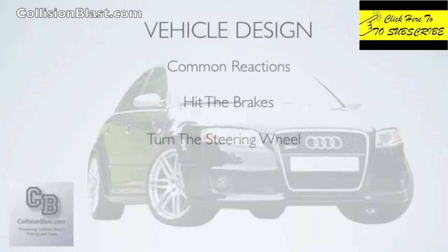The second thing that you're probably going to do, just out of natural reaction, is swerve one way or the other. So you're probably not going to hit them straight on. You're probably going to swerve the wheel just a little bit, and by doing this, it's going to cause the front end to go one way or the other, and that's going to give you side sway. And as the collision continues, the momentum continues to collapse. It's going to cause the unibody to mash, which is going to shorten the frame wherever the point of impact is. And then, of course, if it's hit hard enough, you could get into diamond and twist.